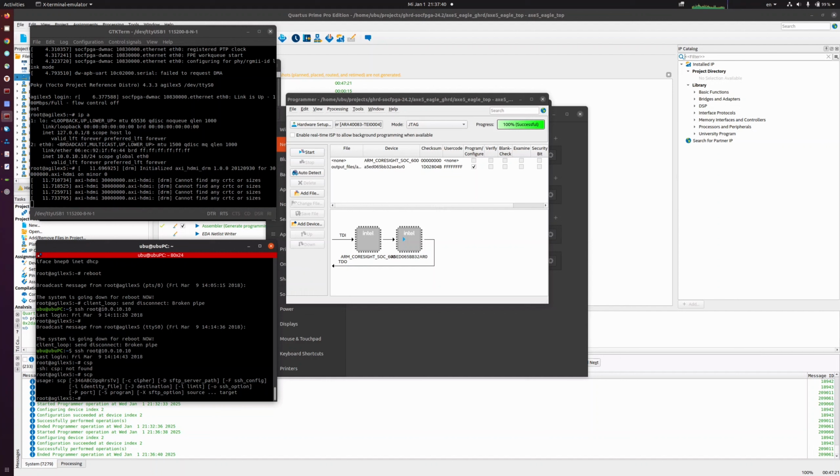Because now I can write a script to compile my code and then transfer it via SCP to the embedded Linux. And on the embedded Linux, then I can do my mmap tests. This is good. Okay, now create.